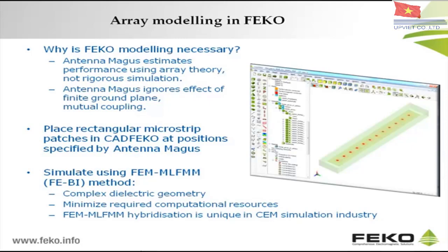At only 1.5 mm thickness, this presents a simulation challenge to integral equation-based simulation methods that discretize surfaces. We will use FEKO's powerful finite element differential equation-based simulation method to simulate this geometry. FEKO's implementation of the finite element method utilizes the FEBI method as a boundary condition to the finite element region, minimizing the dimensions required for this boundary. FEKO further accelerates this simulation by treating the integral equation boundary with a multilevel fast multipole method, which is unique in the electromagnetic simulation industry.